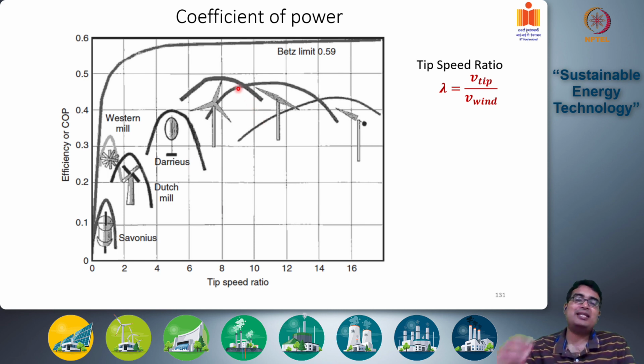So the tip speed is 8 times the wind velocity, and its efficiency is also highest among all possible wind turbines, and it reaches around 0.5. Okay, so what is the case here is that a three-bladed wind turbine has the highest efficiency and also has a reasonable tip velocity, so that its angular velocity omega is not too large that it puts unbearable strain on its rotary bearings.